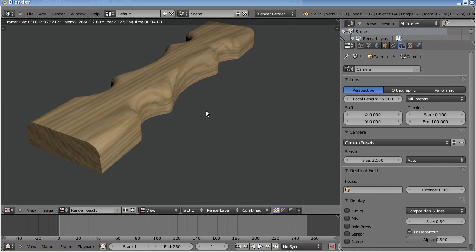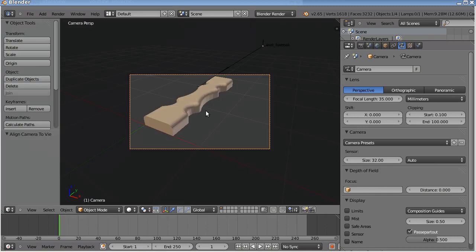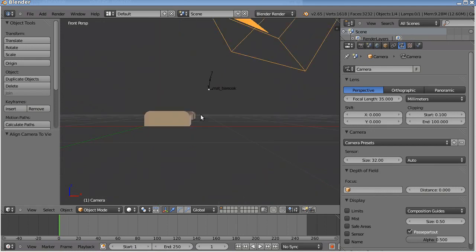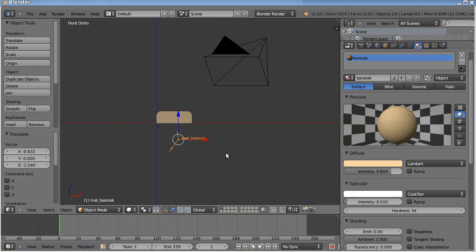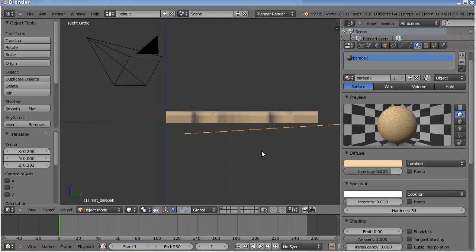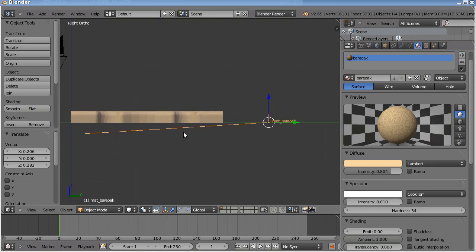You need to set up all the system as you want. I will show you one thing more. Let's go to 1, mark the empty here, and this one says where the center of the wood structure is. So grab it here. I will move it down here. 5 is the auto mode. Grab it to the center. Rotate with R so we get exact mode, and grab it to one of the edges here.